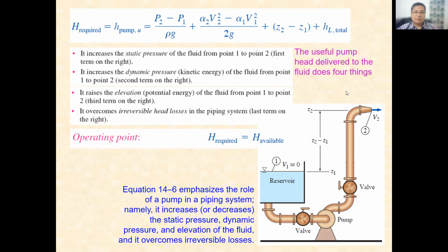Okay, let's see one example. When we design, the pump is in the middle here, and then we provide a mass of instruments inside, so it will contribute to the head loss. We have already learned about this one. The mass of instruments will increase head loss. Yeah, so every part will increase the head loss.